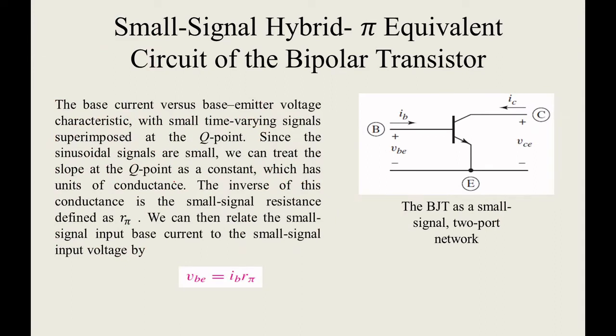Now, before you go to the small signal model, the first thing is I want to remove the DC part, then I want to short circuit the capacitor, then third, you are replacing the transistor with the mathematical model. That is very important. That is an internal mathematical expression of your transistor.